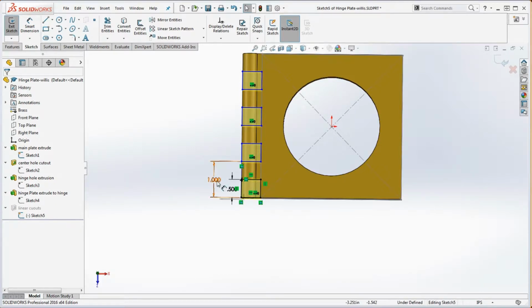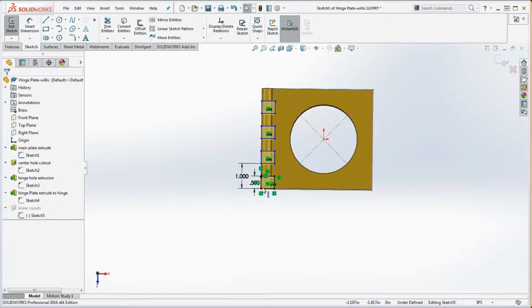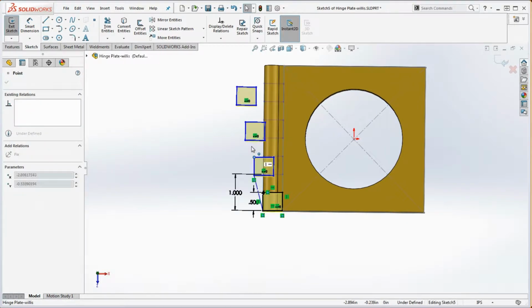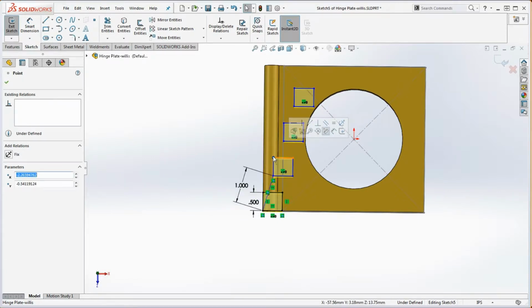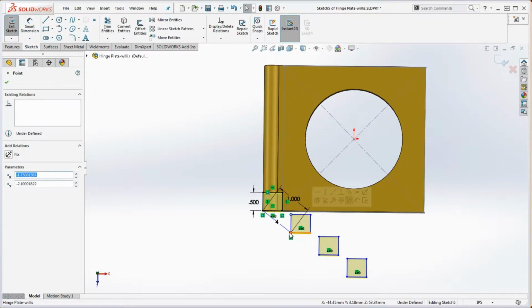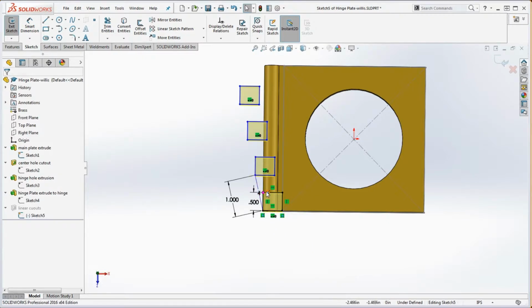Well, he started out pretty good. He's got a 1-inch dimension on this, and he's got some reference geometry in here too. But the thing to do here is to grab one of these endpoints and pull on it and see what you need to do. So right away you can see what you need to do. It looks like the distance relationship's okay, but I can rotate about that because you're only dimensioning between 2 points. And when you dimension between 2 points, it could quite literally rotate around that. But if you wanted to put a real dimension between it, maybe between that line and this line here, that would probably solve that a little bit better.